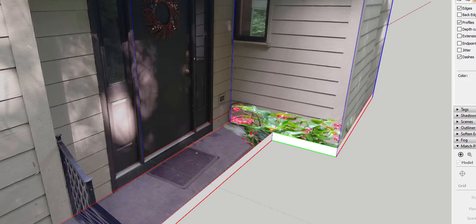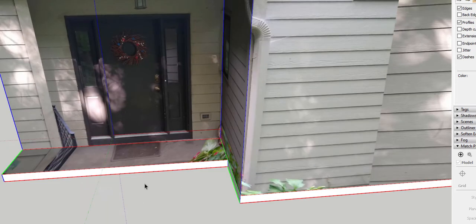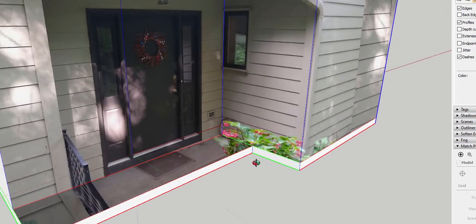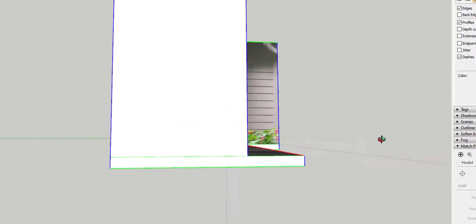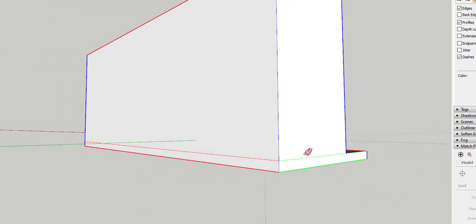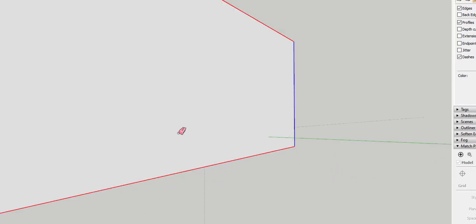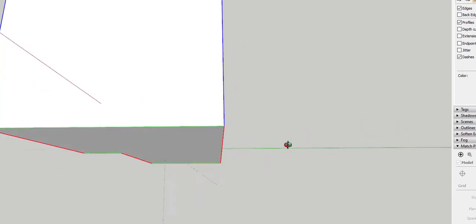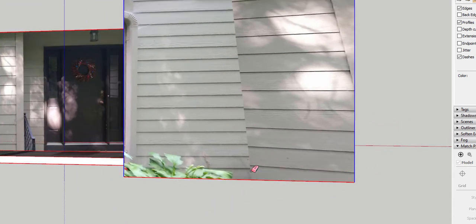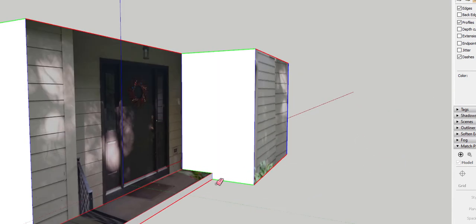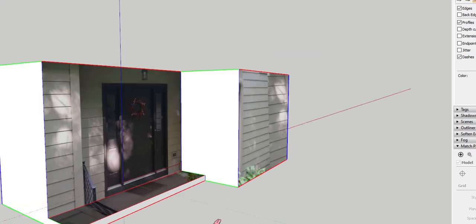I'm just going to go ahead and push-pull this out. Again, I took an actual dimension, so we know it's 27.5. So I'll just do half an inch more, and we're ready to go. We're good for that. Again, clean up. See those lines there? Just clean them up. Clean them up as you go. It becomes a little tedious perhaps, but at the same time, it's going to be helpful in the long run. We don't need these lines here, so let's get rid of them.